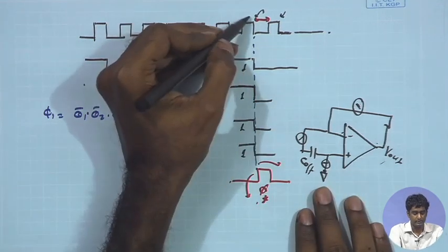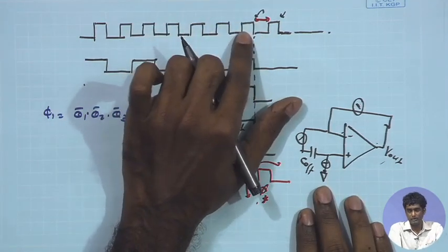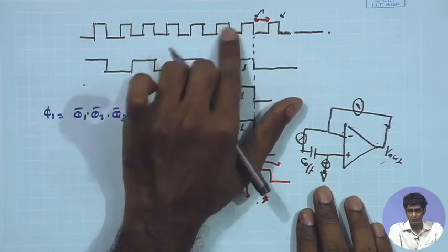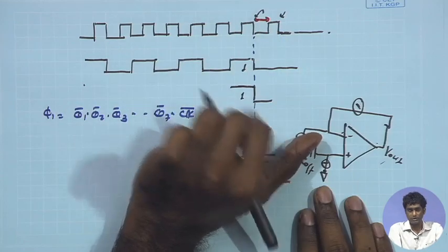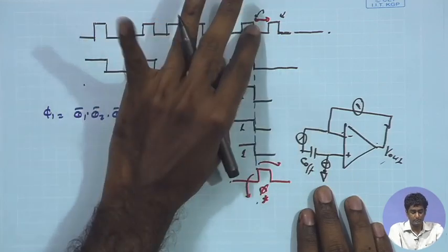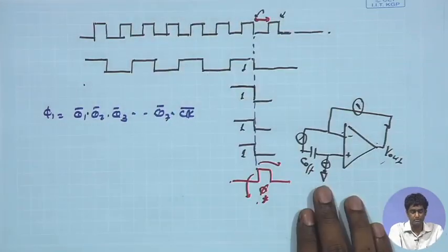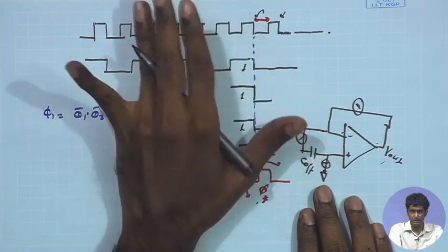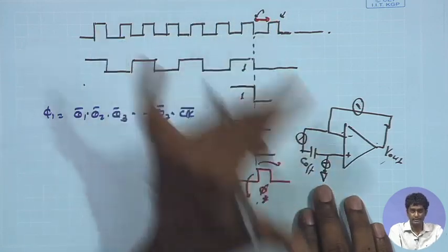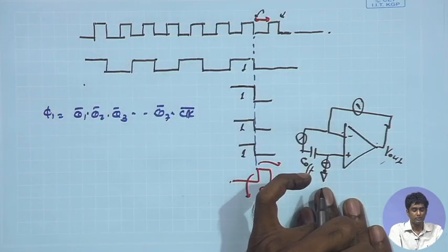Even if you are using this low duration, for example, having 250 kilohertz of clock, and you are using this 4 microsecond of duration for sampling the data onto the sampling capacitor using the switches, even a minimum size switch would be able to meet that constraint. You can slightly increase the switch dimension, of course, to meet that.